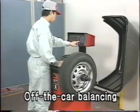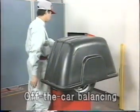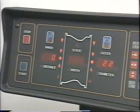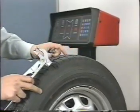Confirm that the wheel balancer functions correctly before the check. Correct the static and dynamic balances by taking 0 gram as the target value. It is important to use and fit balance weights which match the wheels so that they do not fall off while driving.